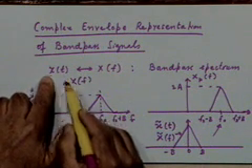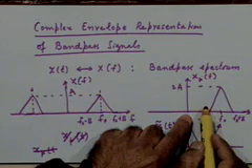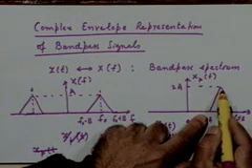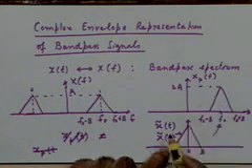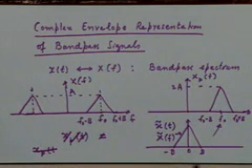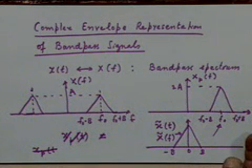We represented x(t) in terms of x_p(t) as the real part of x_p(t), which is still band pass. We represented x_p(t) in terms of x tilde(t), which is low pass. x tilde(t) being low pass means x_R(t) and x_I(t) are both low pass signals.